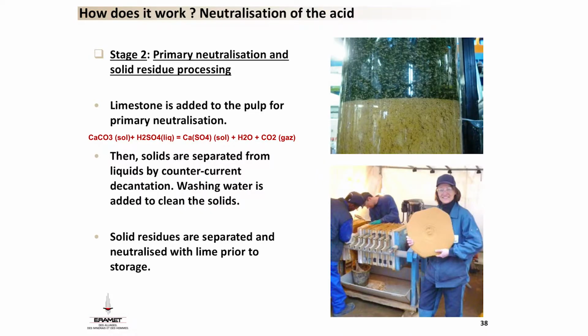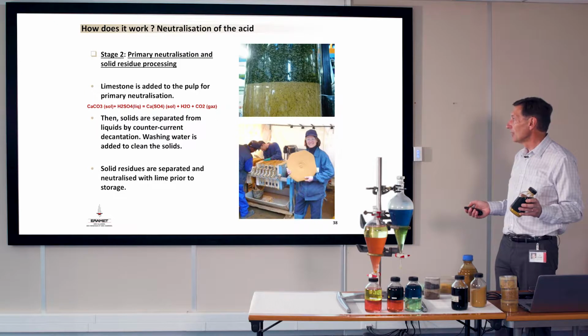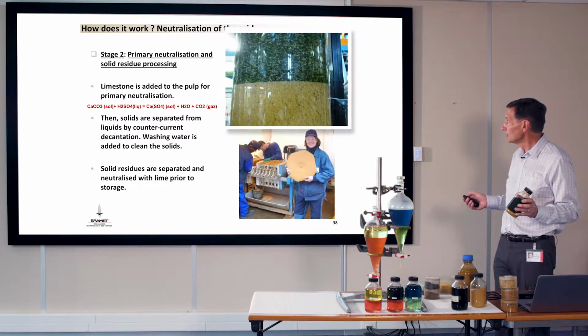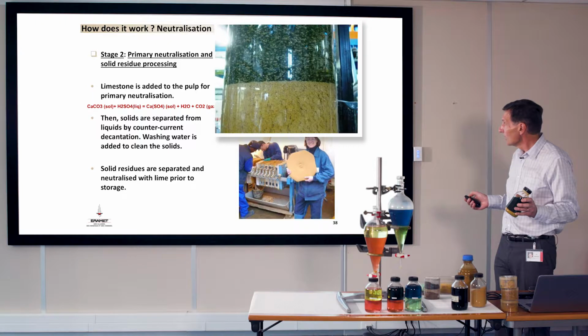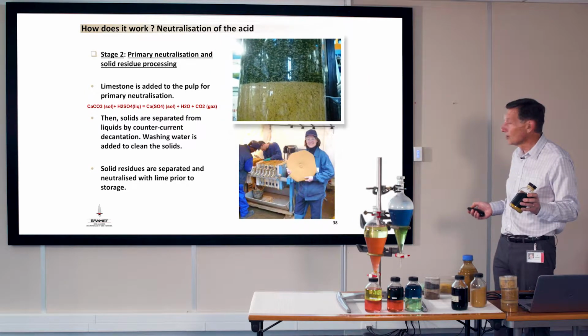After this dissolution part, you neutralize the solution by adding limestone, calcium carbonate, in order to neutralize the remaining acidity, and you form gypsum, a solid, mixed with jarosite, and you separate it by countercurrent decantation. You see here the solution and the decantation of the residue, the small flux of the residue, and the thickening of this residue on the lower part of the decanter.